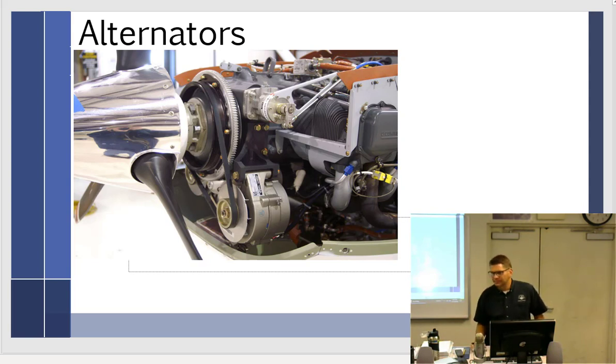Is this a twist back and forth, or is this like an up and down play? No, because the alternator is bolted to the engine. So the alternator should not be moving up and down. It's locked to the engine, right? I just replaced an alternator. I'm talking over here. So it's locked to the engine, but it's driven inside, internally. And so you want to see how far the alternator will turn. The rotor will turn without the engine turning.